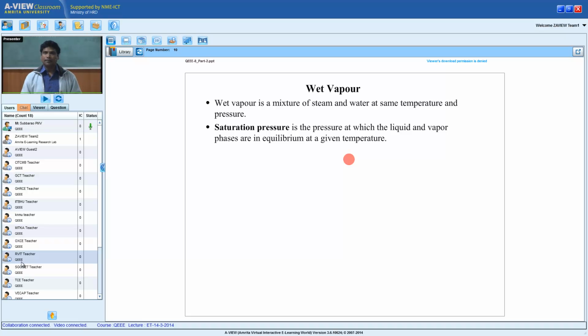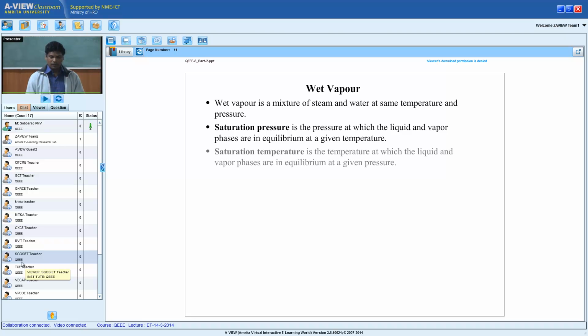That's how people found a couple, made for each other, to create a mixture of these two. One is called the saturation pressure: for a given temperature, there will be a pressure which gives you both phases. Or I can think the other way, what is called the saturation temperature: for a given pressure, I can find the temperature that creates a mixture of these two.